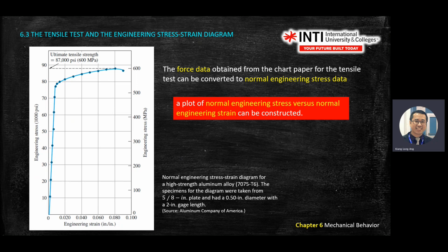Then the x is your strain. Recall Hooke's law. What is Hooke's law? Stress equals Young's modulus times strain. You get your Young's modulus from the graph. Once you plot the graph, stress versus strain, you have all the dots. Maybe it goes haywire, snake-like, like that.